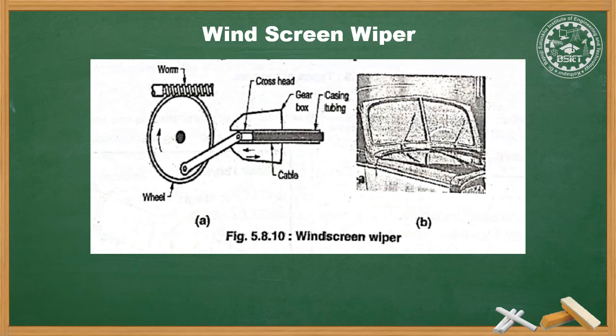A helix formed around the cable constitutes a rack and wheel gearbox. The cable passes through two wheel boxes at the wiper end of the unit. The worm arm spindle is carried in a bearing. The wiper blade is driven by the wheel rotating back and forth in the wheel box due to pulling of the cable rack backward and forward. Most automobiles use two synchronized radial type arms, while many commercial vehicles use a single windscreen wiper.